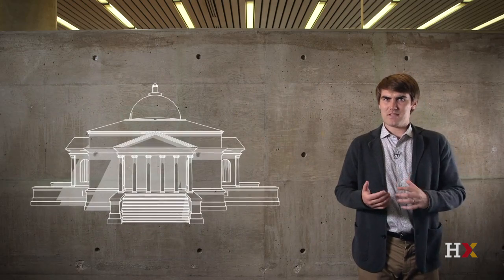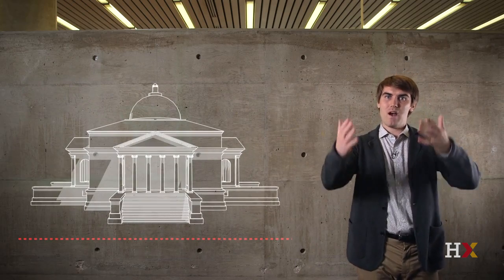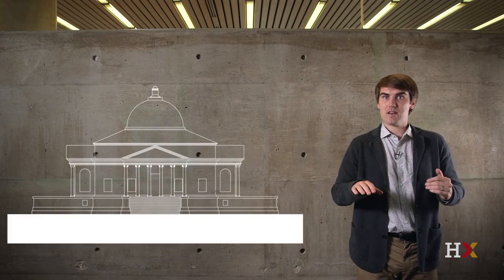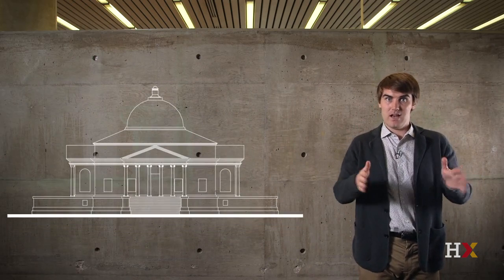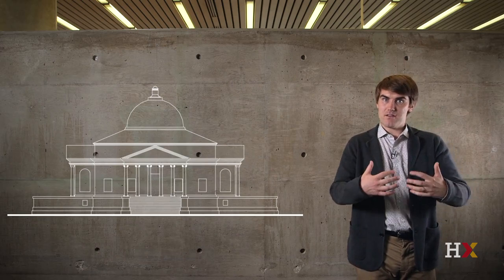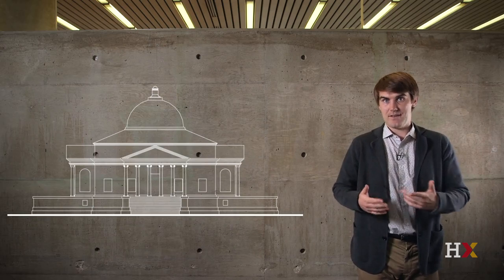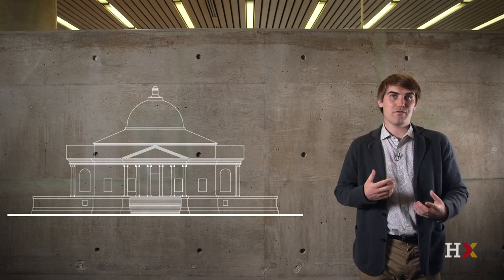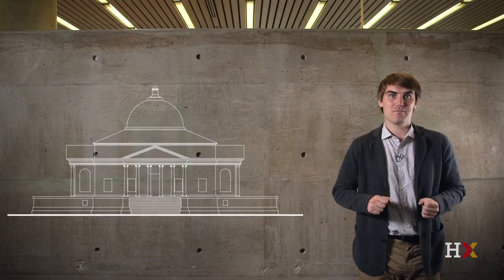The third of the orthographic drawings is the elevation. This is similar to a section, except this time we're cutting well in front of the building. And sometimes on elevations they show the ground being cut, and other times it's more just a line that the building's sitting upon. Here everything is drawn in the lighter line weight because nothing's being cut except for perhaps the ground. The elevation is particularly useful for seeing how the facade has been composed by the architect.